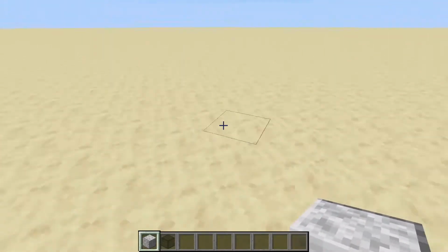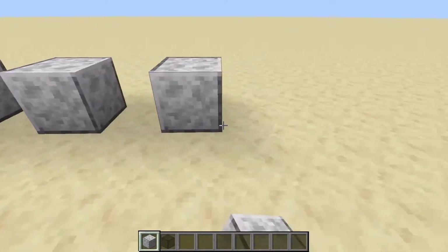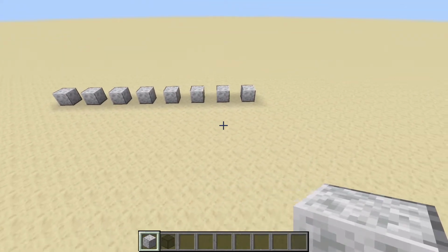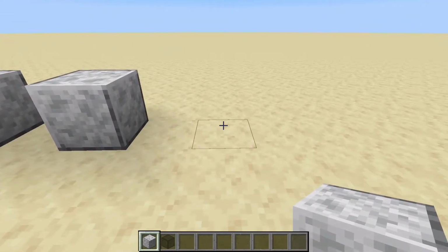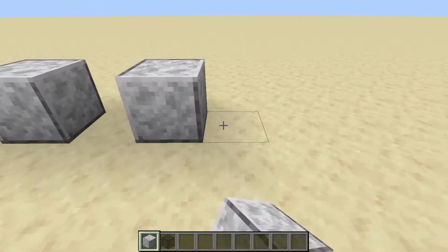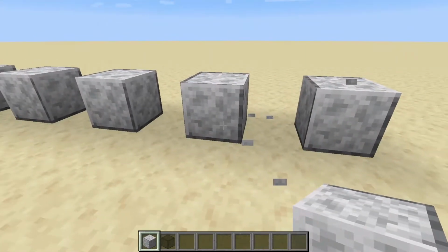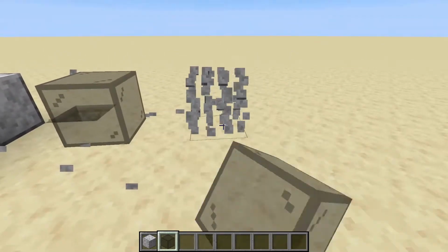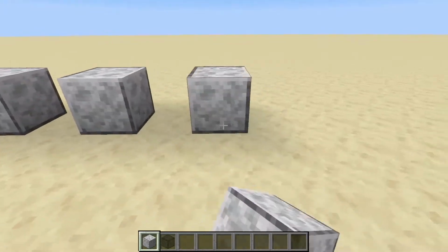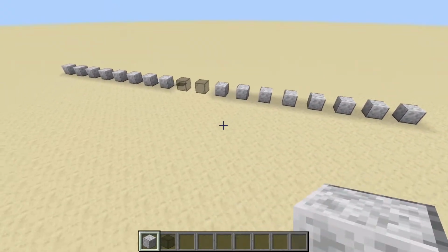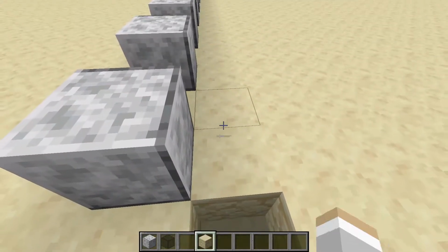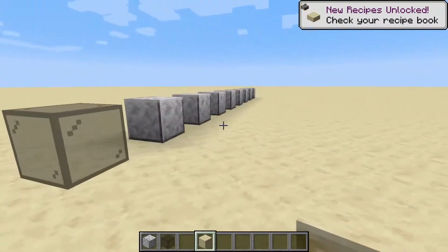So what we're gonna need is 1, 2, 3, 4, 5, 6, 7, 8 bits for an input bus. Then, since this is a ROM cartridge kind of, we don't need read and write. That is unnecessary, so we will make this black. And we will need an 8-bit output signal, 1, 2, 3, 4, 5, 6, 7, 8. And we need one more signal.